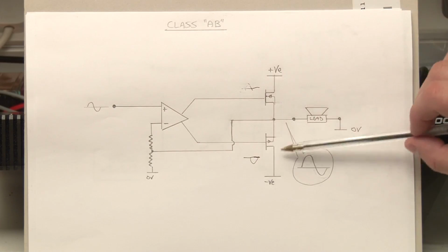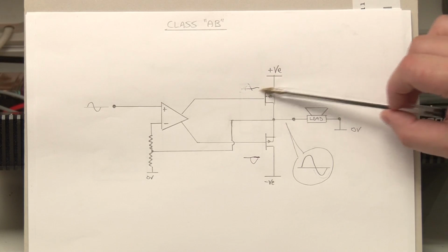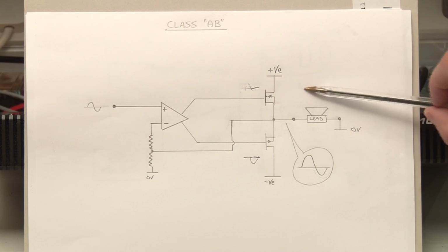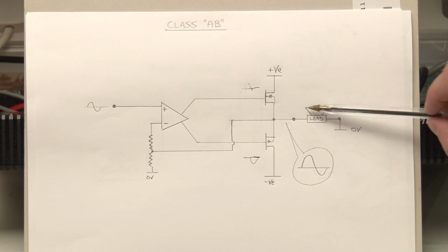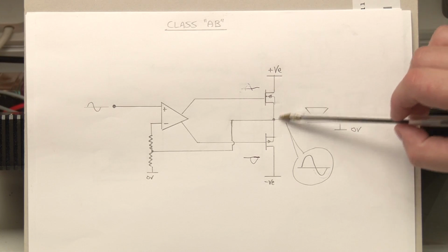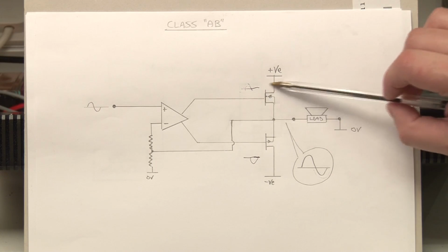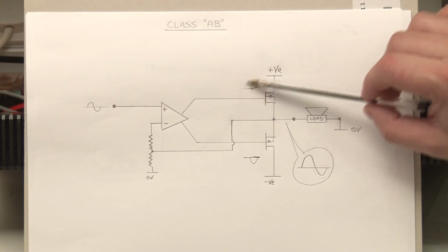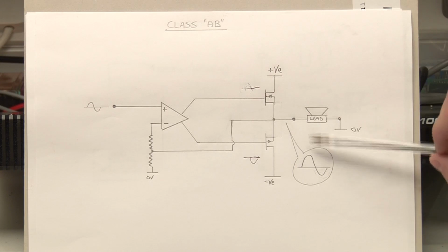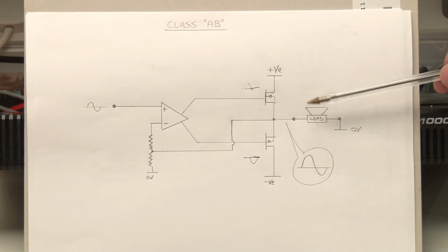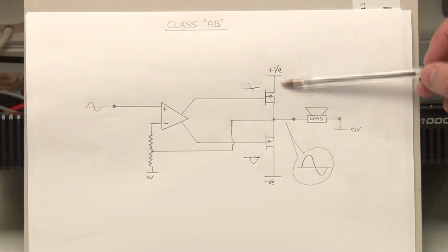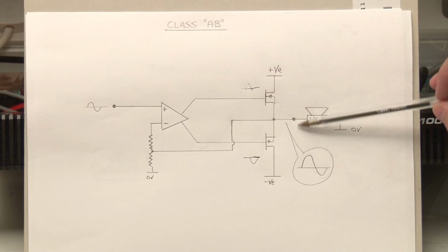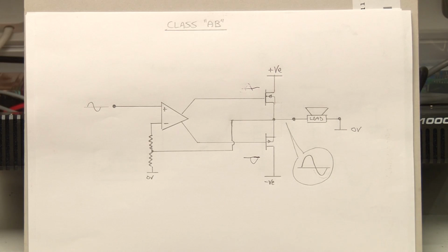One of the issues with higher power amplifiers is that they generate a lot of heat, because the device or devices, if they're in parallel, that are delivering the output power, if this is say 500 watts, then it's quite feasible to be dissipating an equivalent amount of power, about 500 watts or a little less, in these devices, and therefore as heat. So they're pretty inefficient, is the issue with them. Class AB are probably the most commonly used because although they're inefficient, they can be made to be very, very good in terms of performance from a distortion point of view.